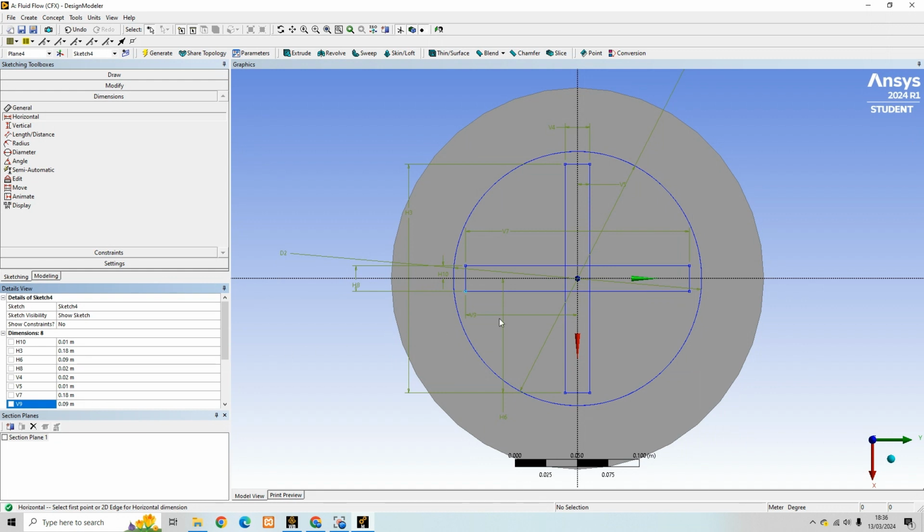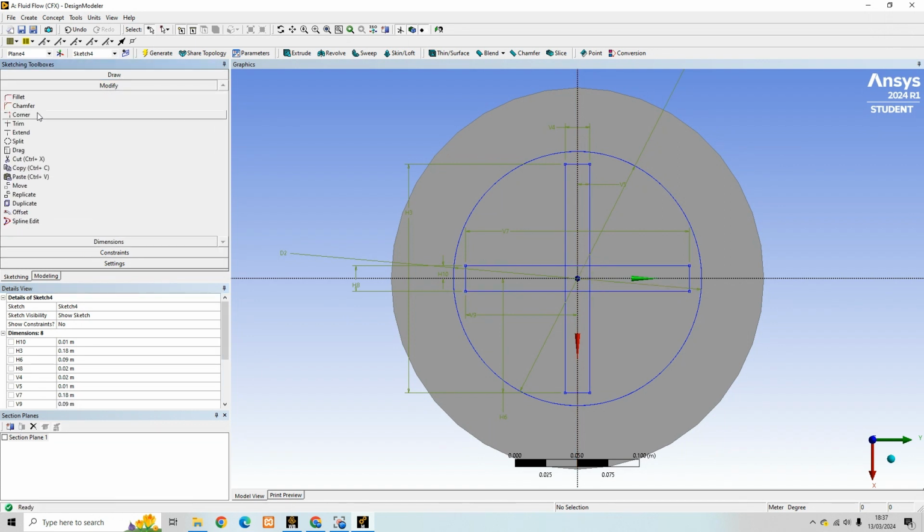There you go. So we're going to extrude this sketch in a minute, but what we need to do first is just break off these edges that are currently in the middle. So we can just do that using trim. In the gaps between either an axis or the outer of the shape, just click once, and it'll remove those, I'm going to call them filling edges, but edges that sit within the middle of the shape. Right.